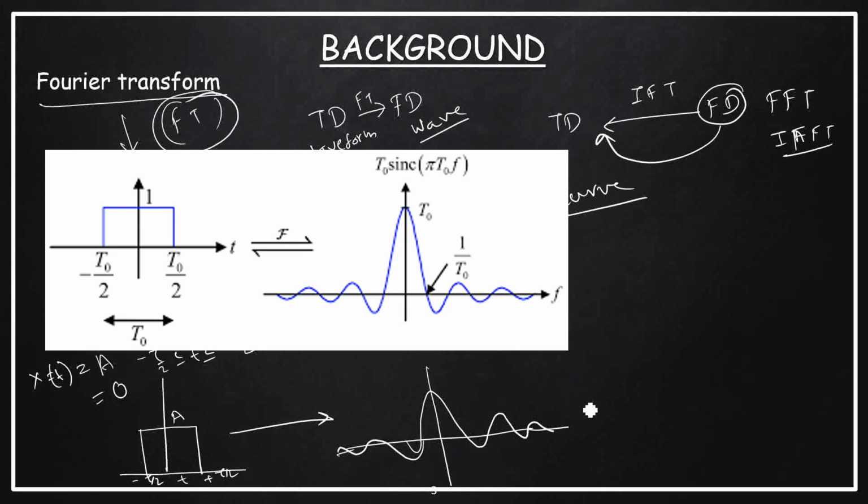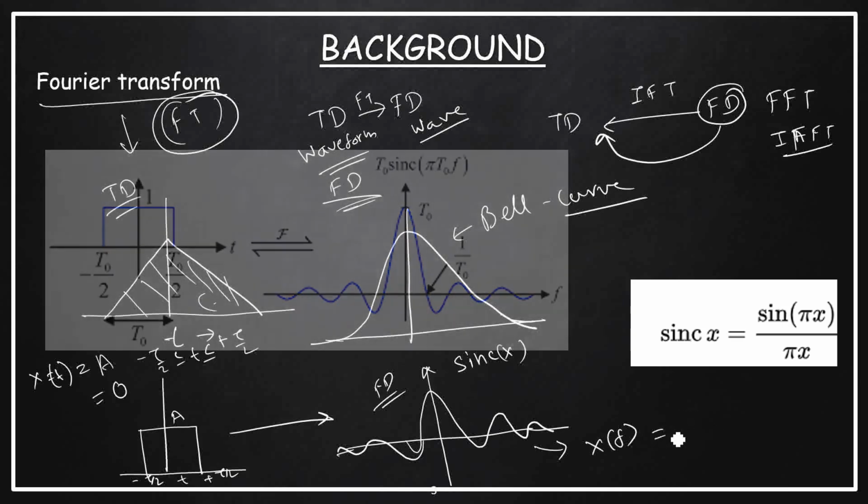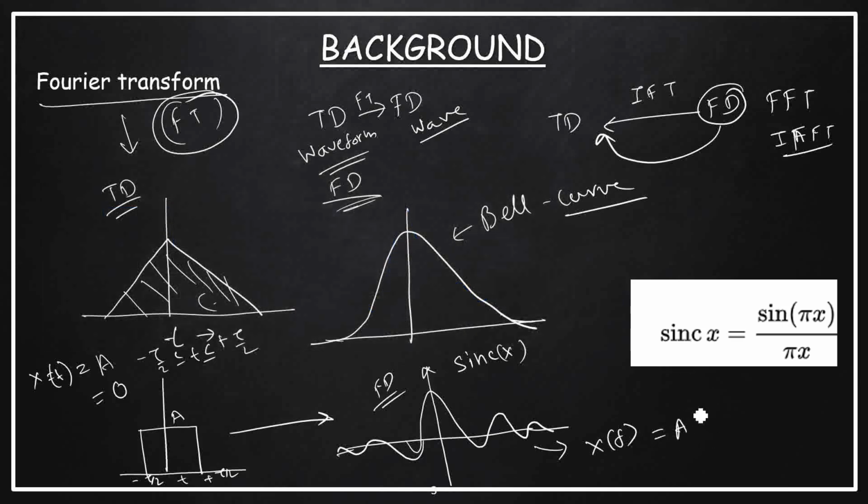And the sinc function, in the frequency domain this can be written as X(f) equals A tau sinc(pi f tau).